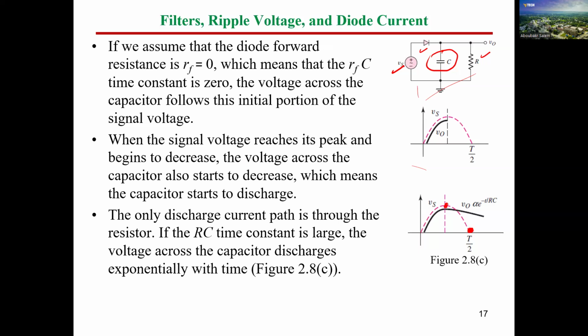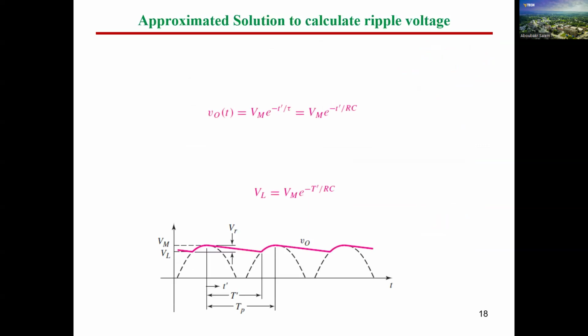So what will happen is the capacitor will continue discharging in the load by means of the time constant of the load resistance and the capacitor value. Until which time, guys? Until the capacitor volt reaches a certain limit. The capacitor volt is still discharging here until the supply volt becomes higher than this capacitor. So what will happen? The diode will be turned on again.